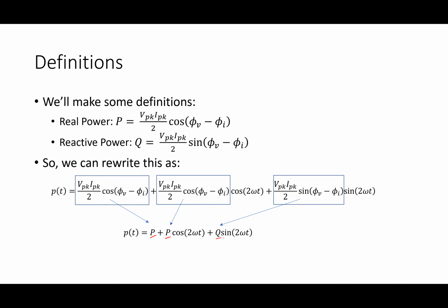The terms that we use: real power is by definition this. Reactive power is by definition this. If I just look at my real power equation, you're used to P equals VI, not true anymore. What do I see? It's the peak value of V times the peak value of I. Is average power and real power the same thing? Average power, real power, active power, those are 3 terms that often mean the same thing.